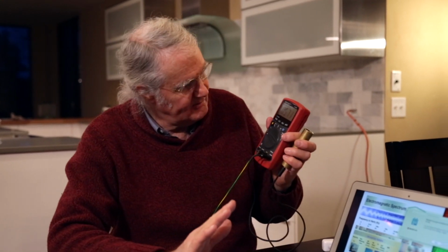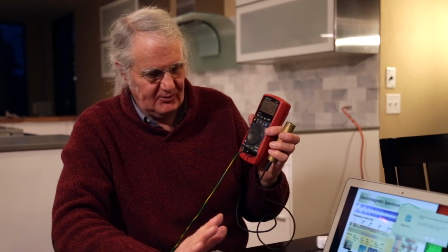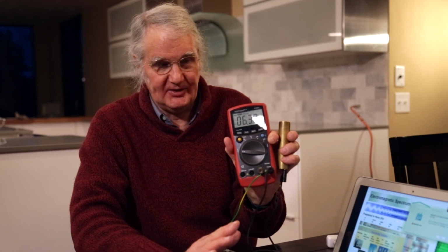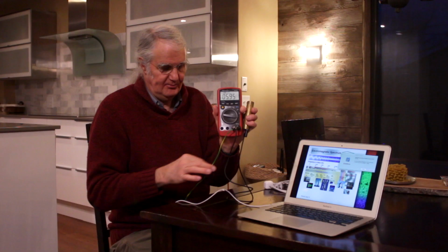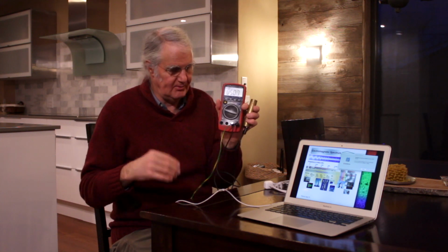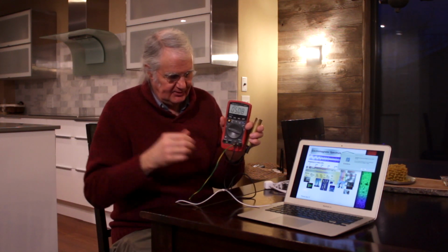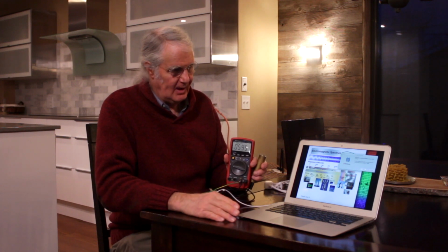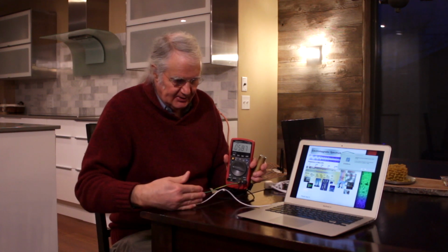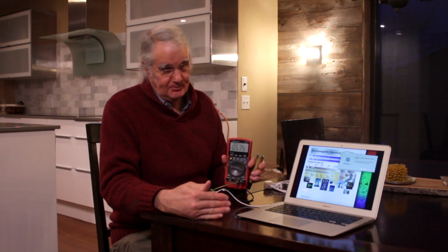So when I just put my hand even a few inches away from this chassis, I'm already at 5,000 to 6,000 millivolts, which is 5 to 6 volts, relative to Earth, because this is our ground. So we're measuring the exposure here relative to Earth. We say that anything above 1,000 millivolts is in the extreme concern level for sleeping areas.